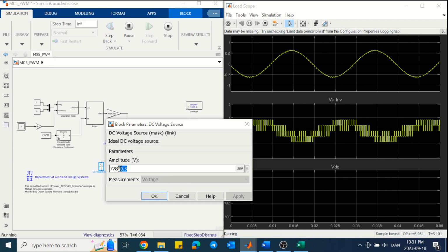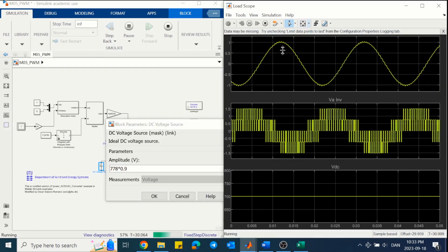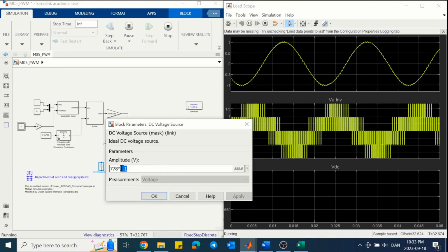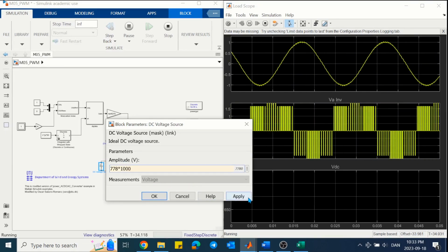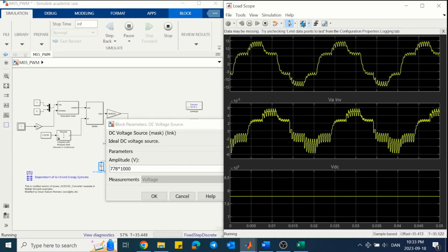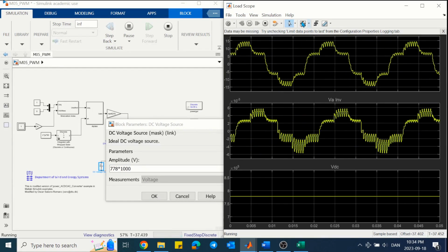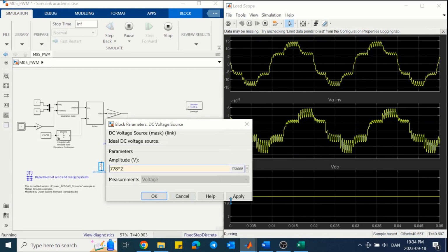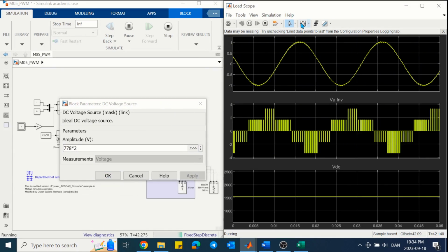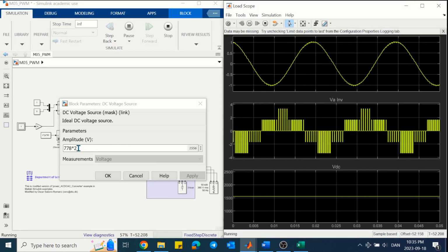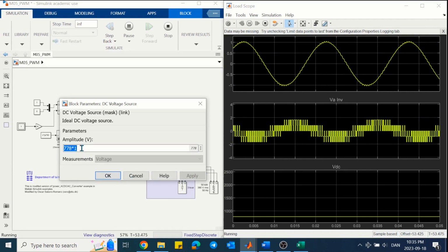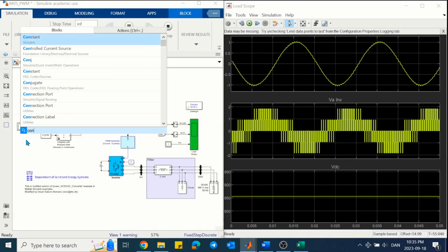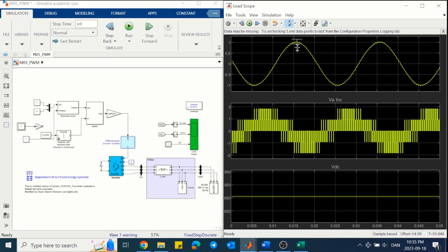Actually, this division is there to compensate for the small deviations of DC link voltage around the nominal value. For example, if you test it for 1000 also, you can see that it's not working properly because the division makes the modulation index very small and the DC link voltage is also very large, which is not realistic. But if we consider around the nominal value, even up to 2 per unit, we can see the impact of the DC link on the output AC voltage is compensated, especially for 1.1 per unit.